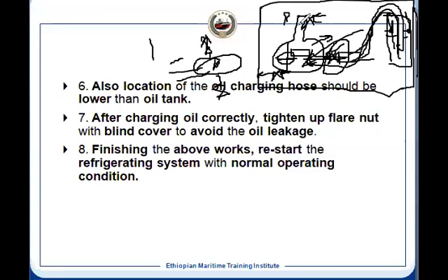We do the pump down after changing the oil? Yes. After that, we do the pump down. Okay, thank you. So the air will collect here. And also, whenever you do the maintenance, another thing, once you do the maintenance, you'll have to charge a little bit, because you have pumped down, you have isolated the system, but some gases you'll be losing. That much you'll have to charge also. So, any other question?